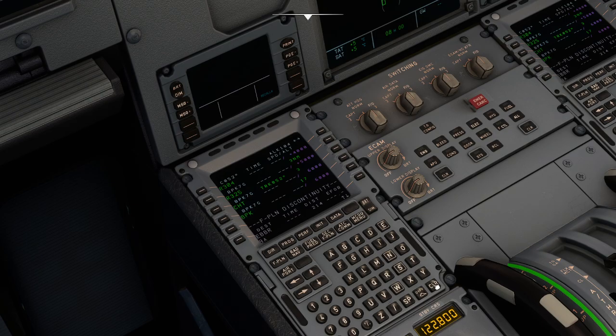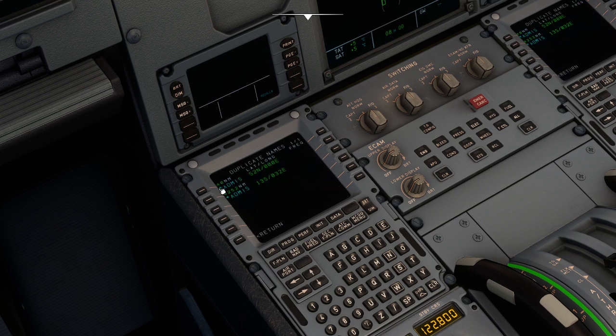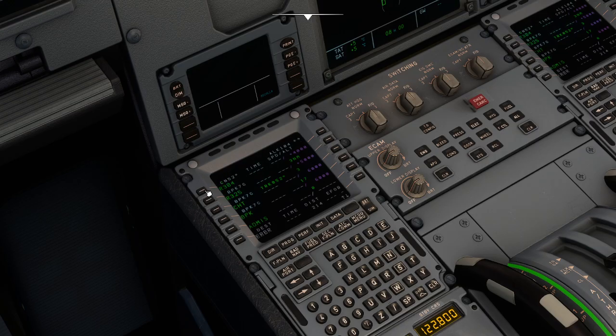Alpha, okay, ADMIS. This is the next one, and we have two options. I'm selecting the one at 40 nautical miles because it is very close. There can be many similar waypoints all across the globe. We can find one or many. And after ADMIS, I'm getting a top of climb, which is 31,000 feet.